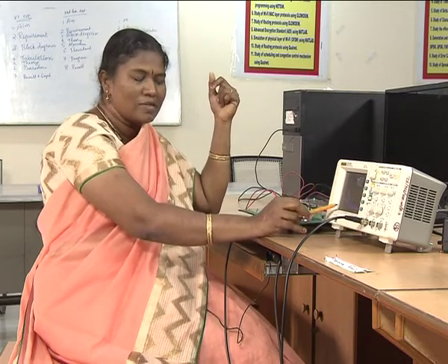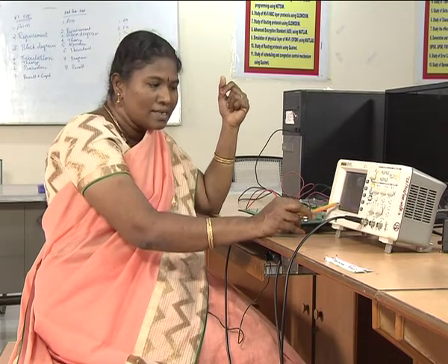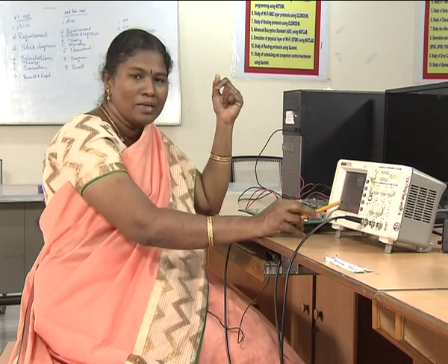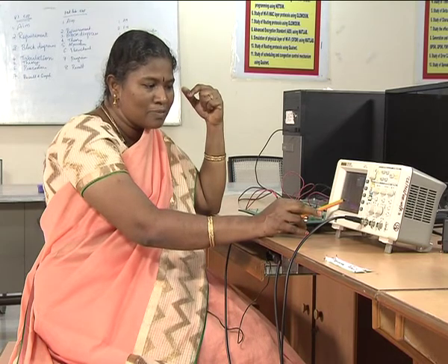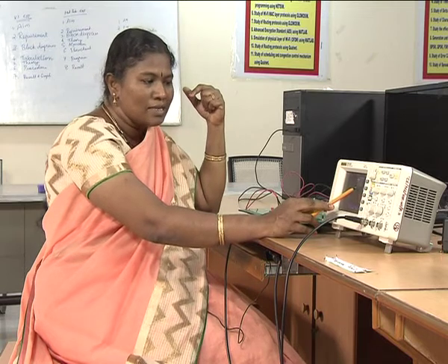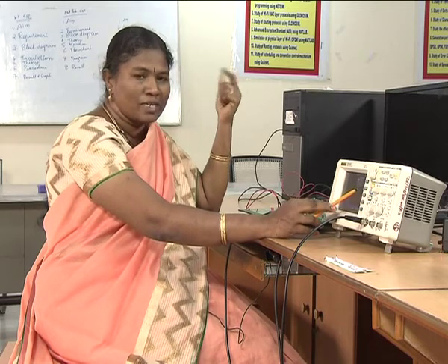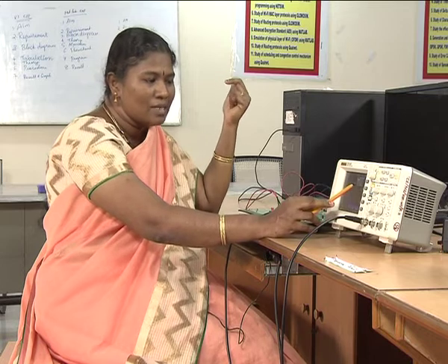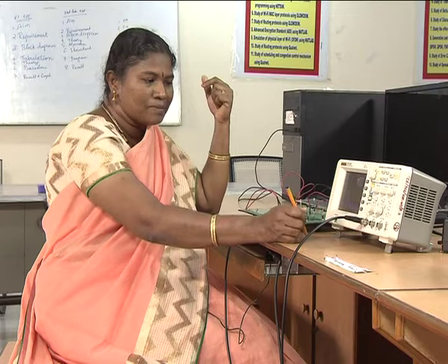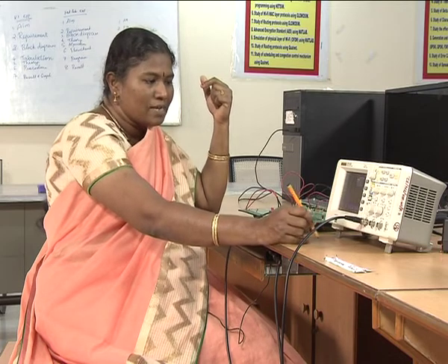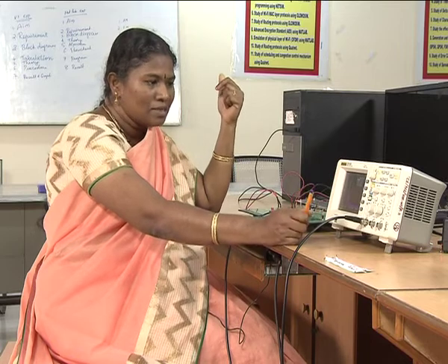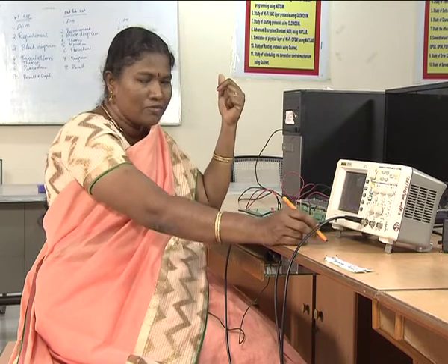In the frequency spectra of the FM modulated signal, compute del f by adjusting the cursors between the first lobe minimum 2 points. Once you keep the cursors between the 2 points, there will be a value called 1 by del x, which gives you 2 del f value as 455 kilohertz. Then compute beta equal to del f by Fm. So, 455 divided by 2 into Fm, which is 5K, so about 10K, and therefore the beta value is 45.5.